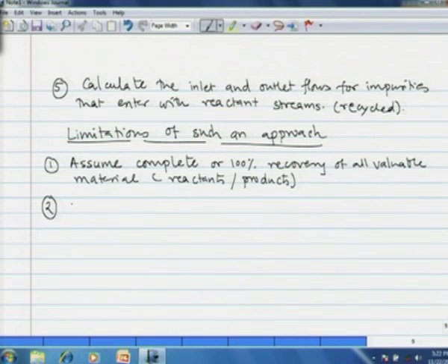Now, it is always more important to find the neighborhood of optimum values of design variables which fix the inlet and outlet flows than it is to include the losses early in the analysis.